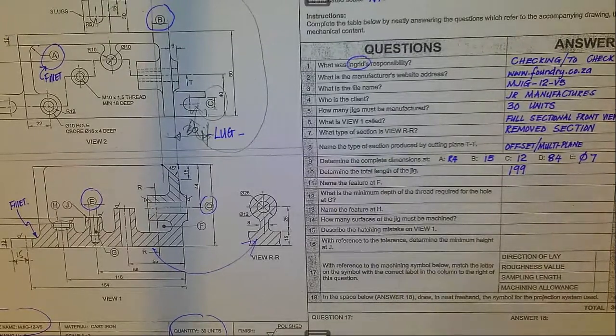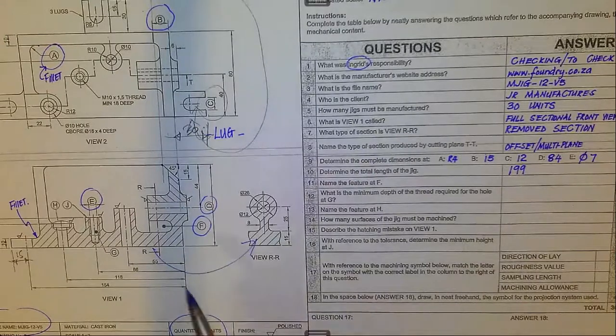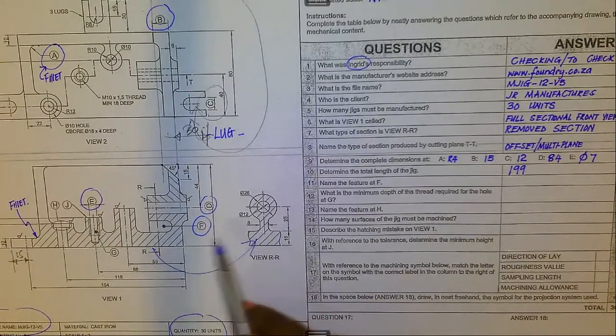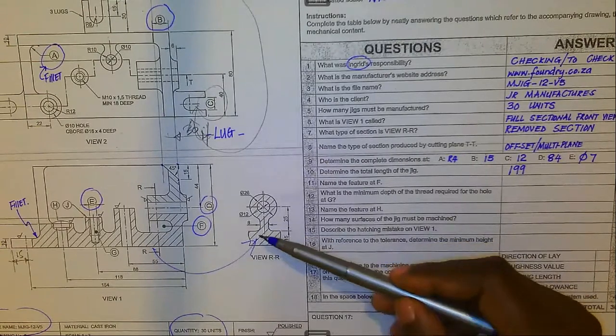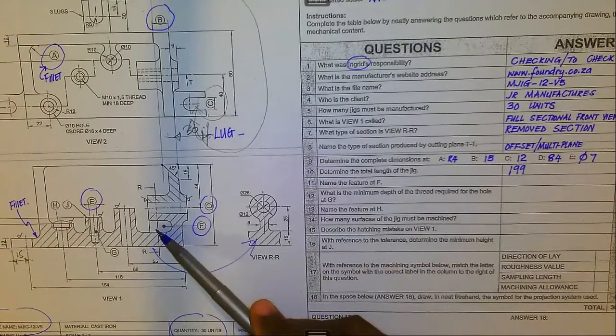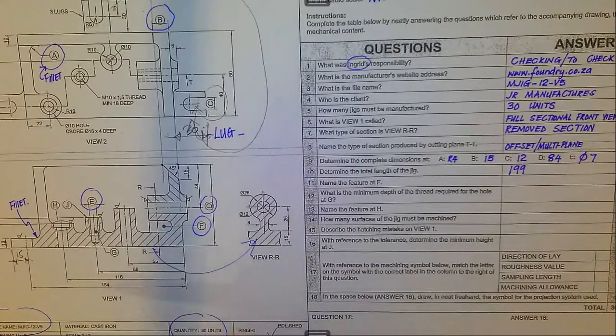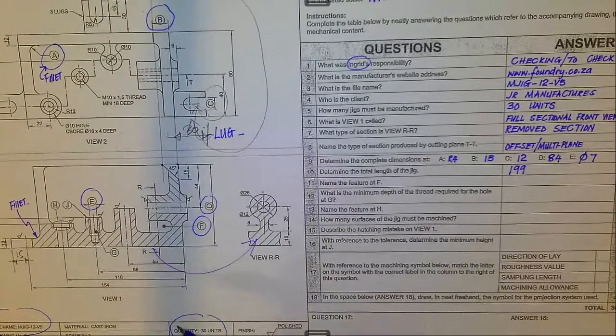Okay. Name the feature at F. The key there is to look for point F. Here it is. That is our point F. If we look at this, we have got that. If it is not hatched like that, but as you can see, this side is hatched. Now, there is a rule. If you cut this particular part of a machine, or a component of a machine, you are not going to show it in section if you cut it along, but if you cut it across, you would show that one in section.